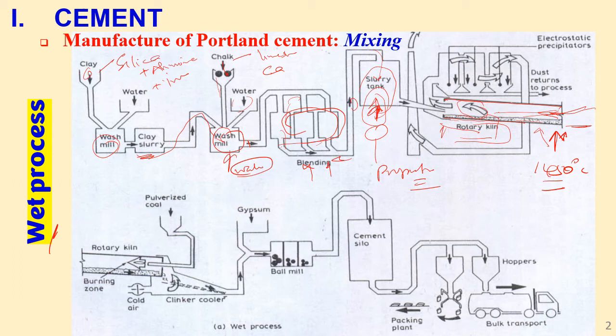So at this upper end, as the slurry moves downwards, first the water is driven off and carbon dioxide is liberated. So at these temperatures, assuming it was 0, as it continues to rise to 100, 200, water vaporizes and carbon dioxide is liberated. Then the material becomes dry, and a series of chemical reactions happens in this rotary kiln. At the hottest part, about 20 to 30% of the material becomes liquid. So we have liquid lime.